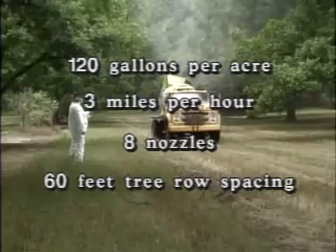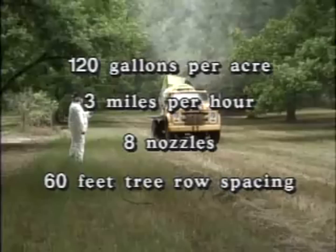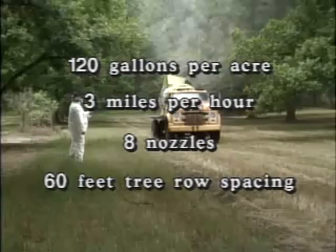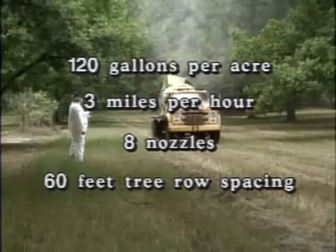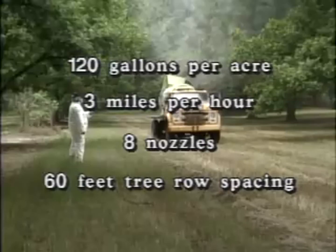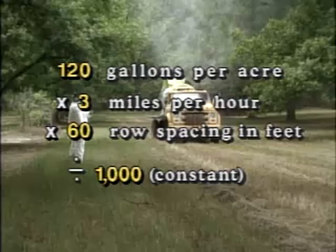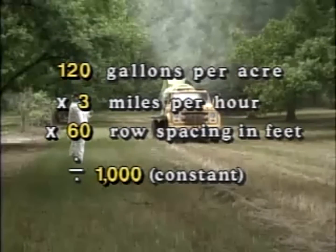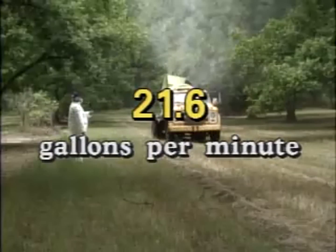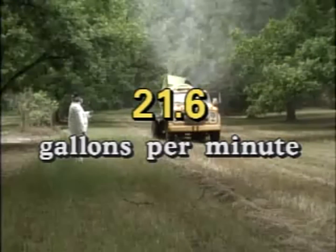Let's say your gallons per acre is 120. You're traveling 3 miles per hour using 8 nozzles, and your tree rows are spaced 60 feet apart. How many gallons per minute do you need? Multiply 120 by 3 by 60 and divide that number by 1,000. That's a constant. Your answer is 21.6. That means you need 21.6 gallons per minute.